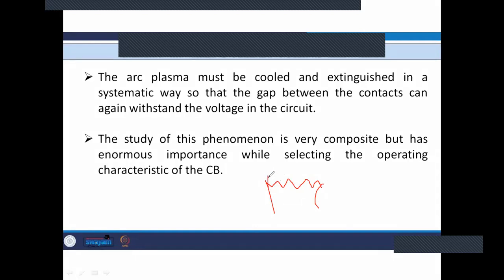By this mechanism, the arc goes up and down in these crests and troughs, so the arc will be cut into fractions. In this way we will get rid of the arc. A fractional arc is of no importance, and there is no danger from it. So this is one of the methods of pinching the arc.